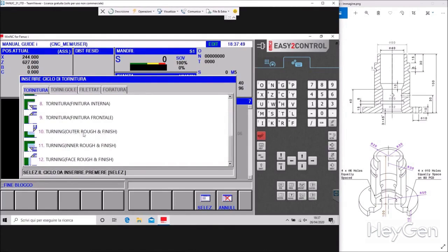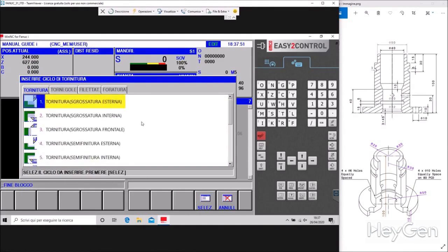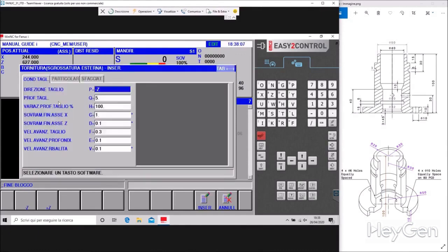What's the point of having roughing and turning with the same tool? It's probably that being aimed at those who make one or two pieces, the wear of the tool is relative. I do the turning and finishing for you with 2 different operations and more. For the simple purpose of being a bit more educational, external turning and roughing, double-click. In your case, it will be an enter.